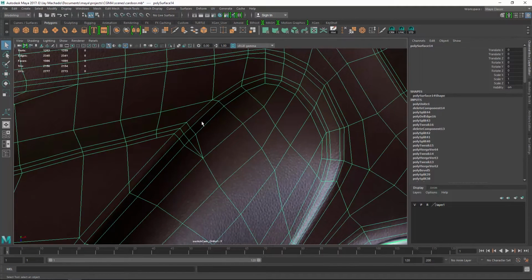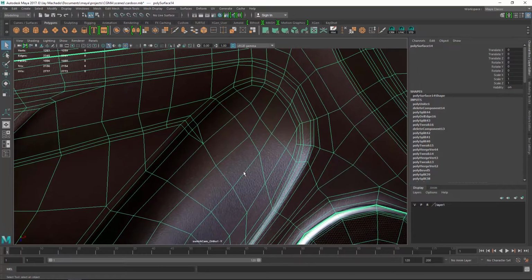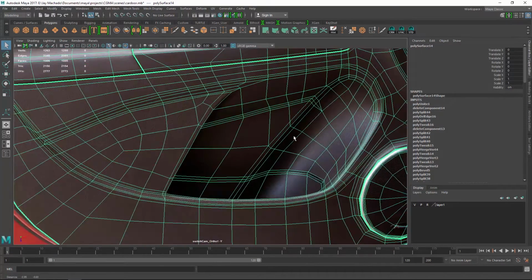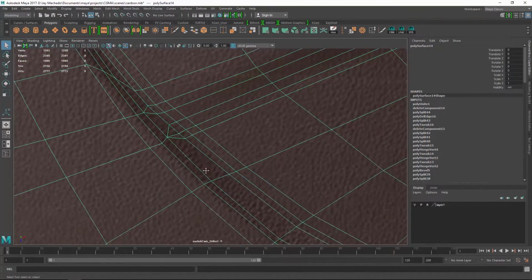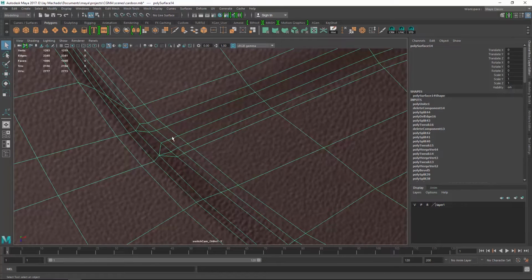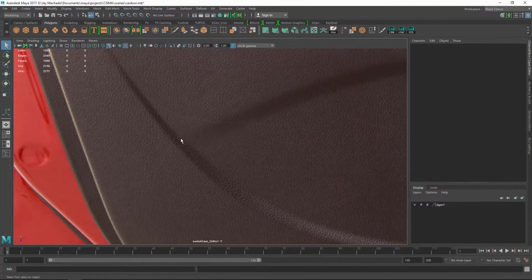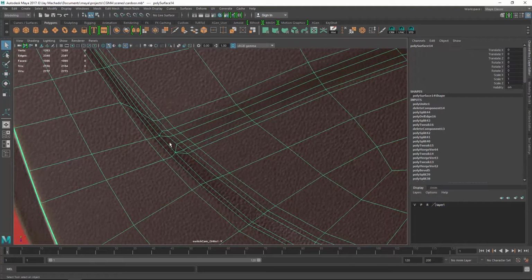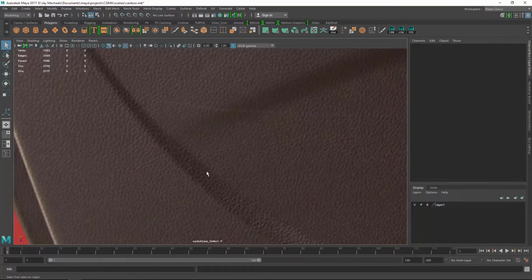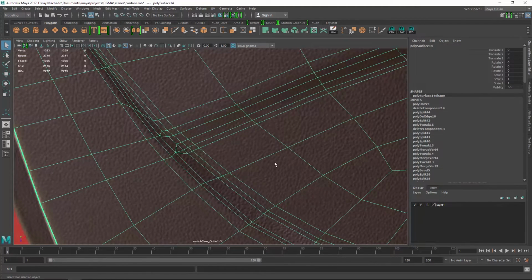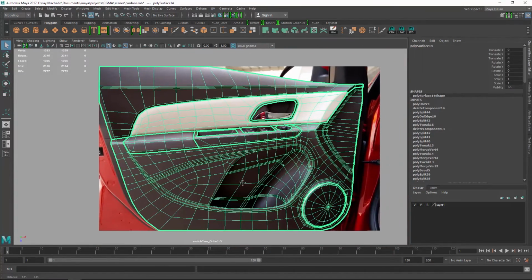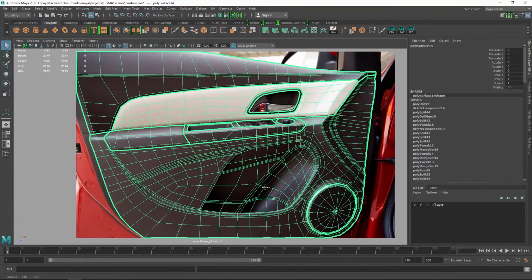You can see these other areas where I've terminated edges. Sometimes if you carry these edge loops all the way through your model, you'll get these weird kinks in your curves. So I find that if an edge isn't going to extend past a certain point, it's best to just terminate it. You can see this edge kind of ends on this other edge. So I just collapse all the edge loops together on a flat plane at that point.